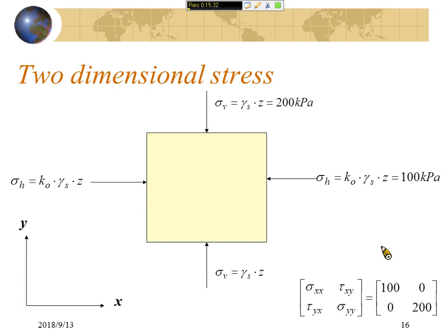You will have principal stress directions in the horizontal and vertical directions, and you have the major principal stress equal to 200 kPa acting on the horizontal plane, and the minimum principal stress equal to 1 kPa acting on the vertical plane. Because it's a two-dimensional analysis, you will have only 4 components for your stress tensor, right?